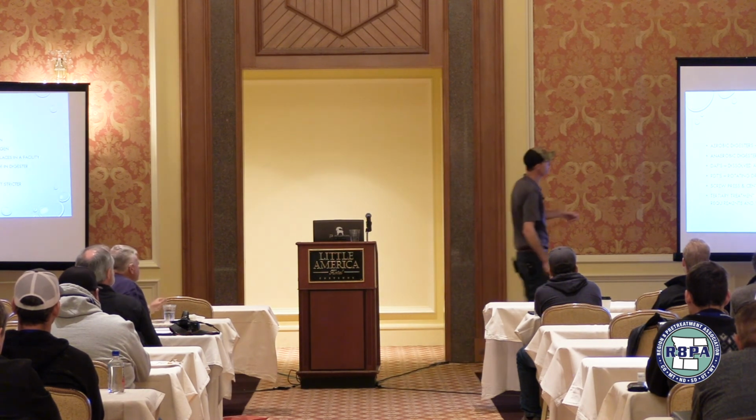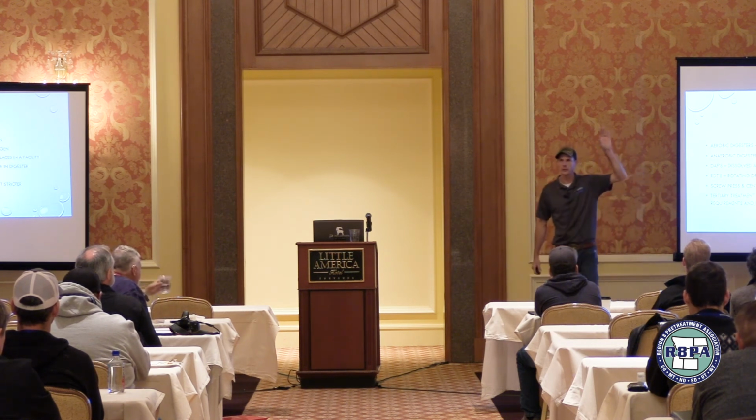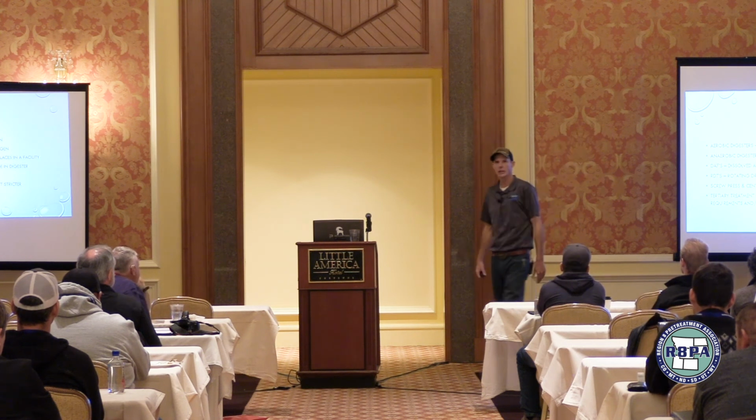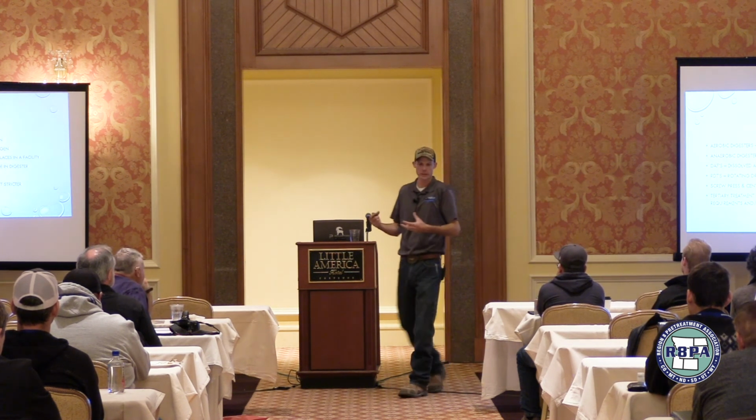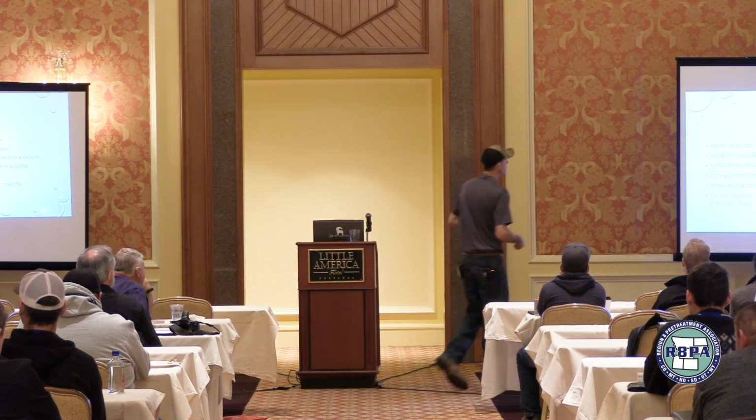If you're at a big plant, you've got a centrifuge probably. Screw presses are pretty cool. Has everybody seen a screw press? Kind of a new technology. Really, really low energy, but it basically works like a centrifuge, dewaters that sludge out of a digester.